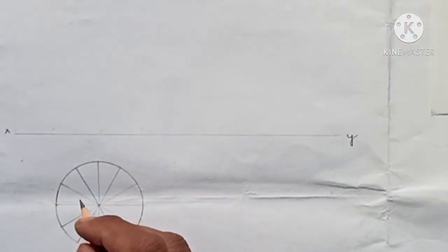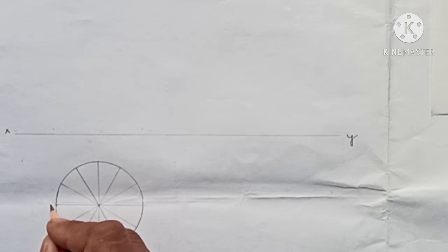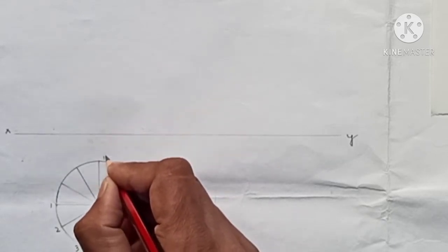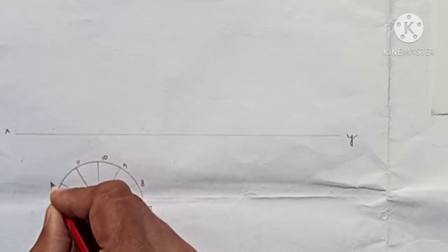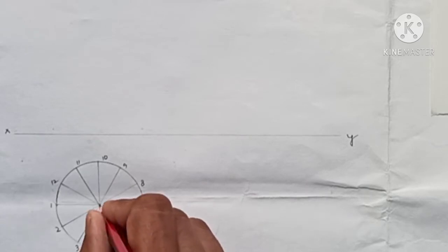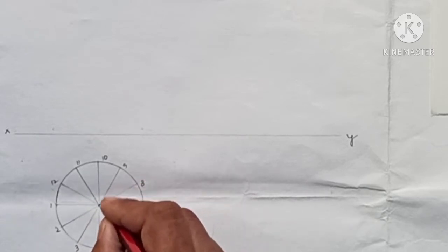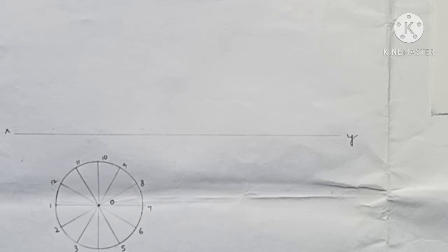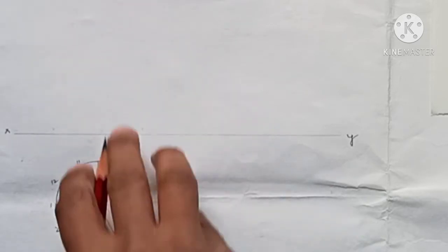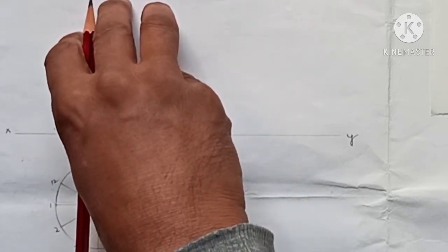Remember, as many divisions as you do with the base, here 12 equal parts. So now let me name these parts. So I'll name this 1, 2, 3, 4, 5, 6, 7, 8, 9, 10, 11 and 12. So this is the base of the cone, and this is the apex or the center of the cone. Let's name this as 0. Fine. So by drawing this, now I can draw the front view. First we need to draw the top view, then I can draw the front view of this cone.